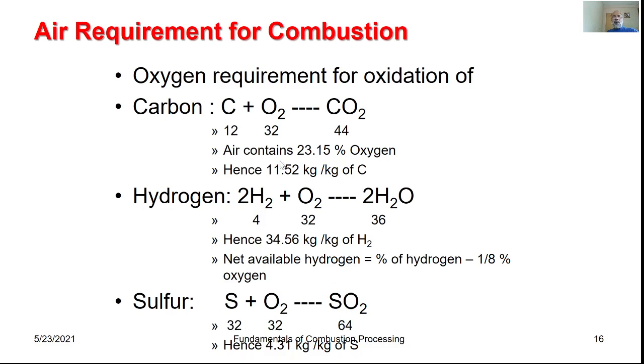As we go through these basic reactions and consider air containing 23% oxygen, for carbon combustion there will be a requirement of 11.52 kg of air per kg of carbon. Similarly, there will be a requirement of 34.56 kg of air per kg of hydrogen.